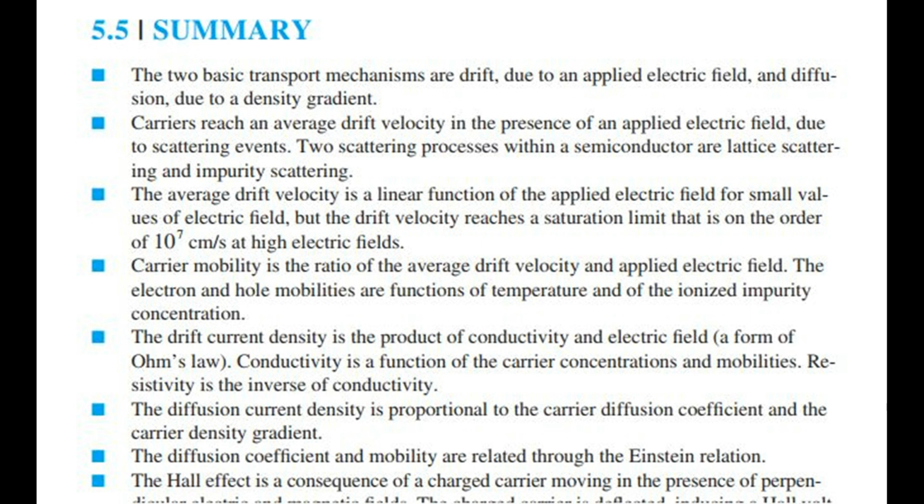The electron and hole mobilities are functions of temperature and of the ionized impurity concentration. The drift current density is the product of conductivity and electric field, a form of Ohm's law. Conductivity is a function of the carrier concentrations and mobilities. Resistivity is the inverse of conductivity. The diffusion current density is proportional to the carrier diffusion coefficient and the carrier density gradient. The diffusion coefficient and mobility are related through the Einstein relation.